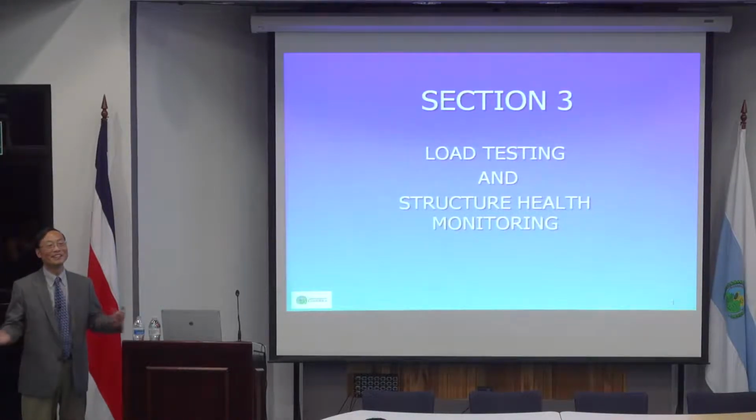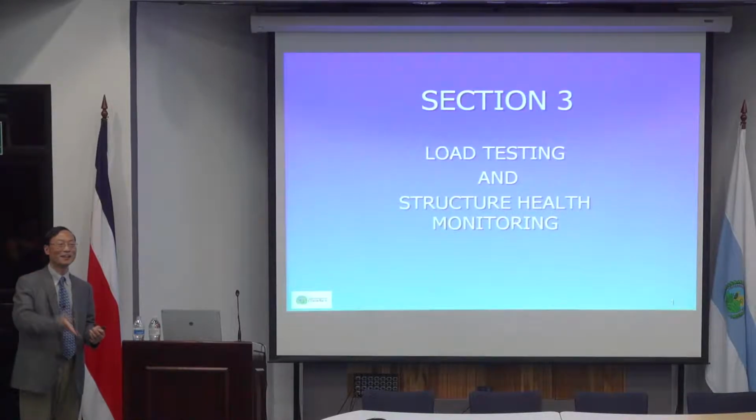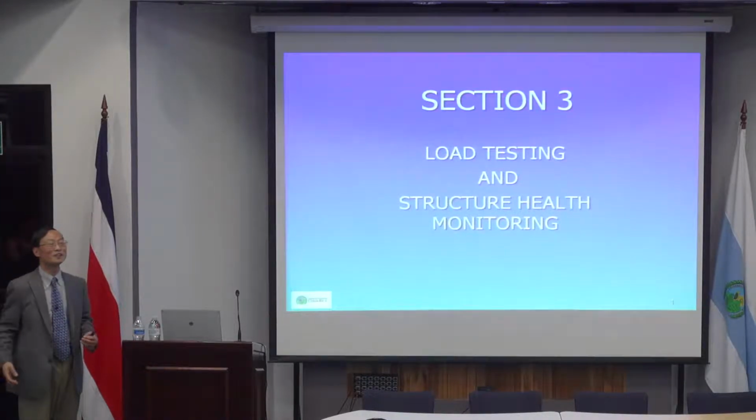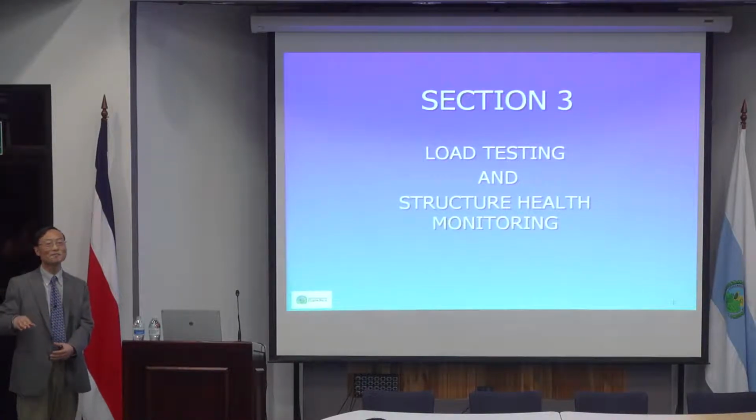If reinforcement and concrete have no bonding, there's no capacity, because the whole basis of reinforced concrete is common deformation or common strain. In other words, we assume plane strain to develop equations, and that's typically true. You say the same thing: if the concrete slab and concrete girder do not separate, they have sufficient bonding. Even if you don't have reinforcement connecting them, they're bonded.